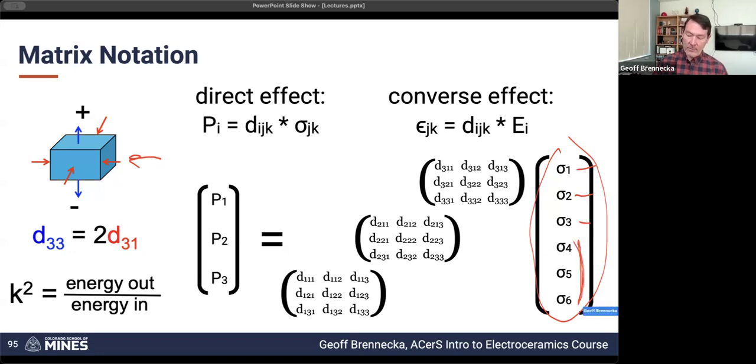And so if you remember from when you learned any basic mechanics, if you stretch on something, just like this, the cube up in the top, then you're going to get strain that's directly responding to that. You can also shear it so that let's say you apply a force here and here, you end up with a trapezoid. I'm a really bad artist, I'm sorry. So by shearing it, you end up with a trapezoid, and those shear components are what are represented down here.